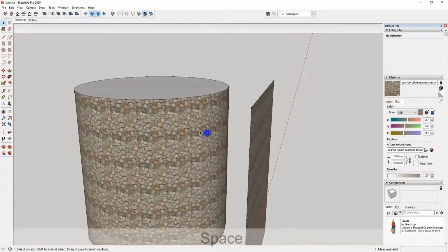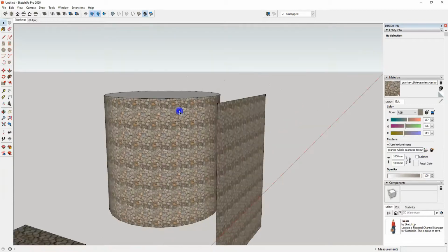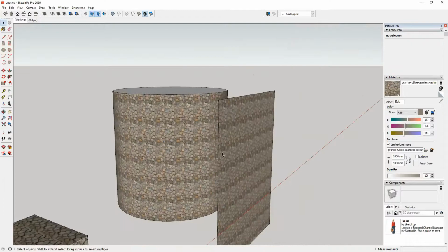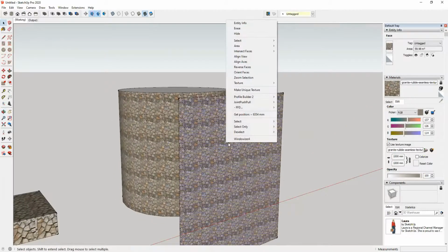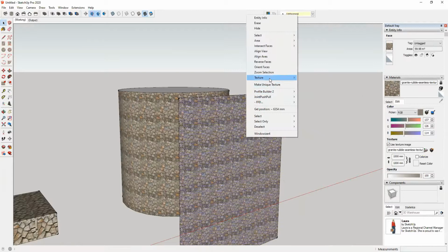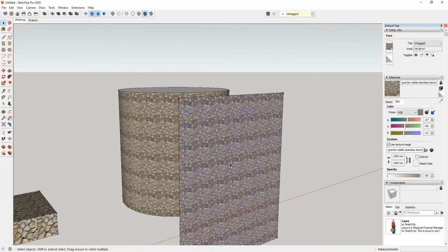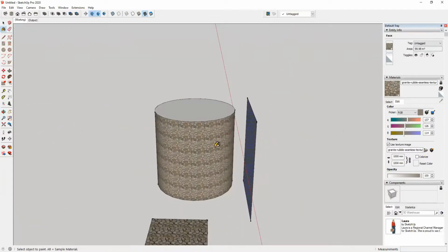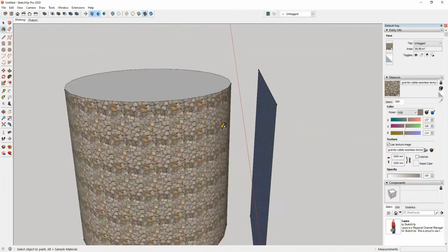So in that case, if that material is not properly applied, now here this is not the right example, it's already applied here. So for that, I will go to texture and turn the projected option on. Okay. Under texture, you can see that the projected is now on. Now this texture is used as a projection. Now, what I mean by that is, using this as the reference, the texture will be projected along the curve.